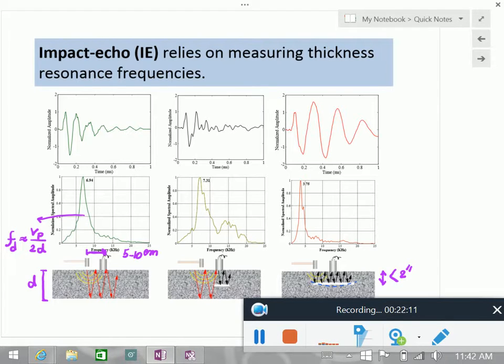For the part where the delamination isn't too long, you have reflections both from the end of the slab and from the delamination. Don't they have two different results on the graph, because it's reflecting from two different sections? Yeah, but they are kind of overlapping. These are also real data from an actual slab. This is not even a single slab.